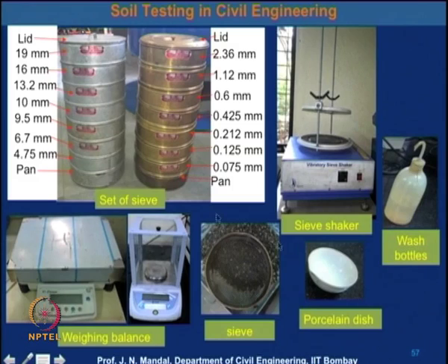One portion of the sieve is shown here, the soil is on the top. And this is the porcelain dish in which we determine the moisture content of the soil. So, these are the accessories required to perform the test of sieve analysis of the soil.